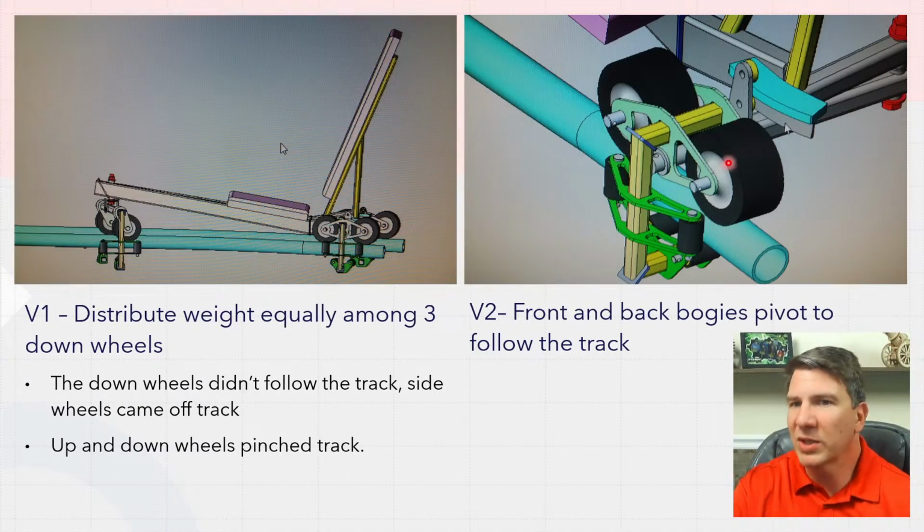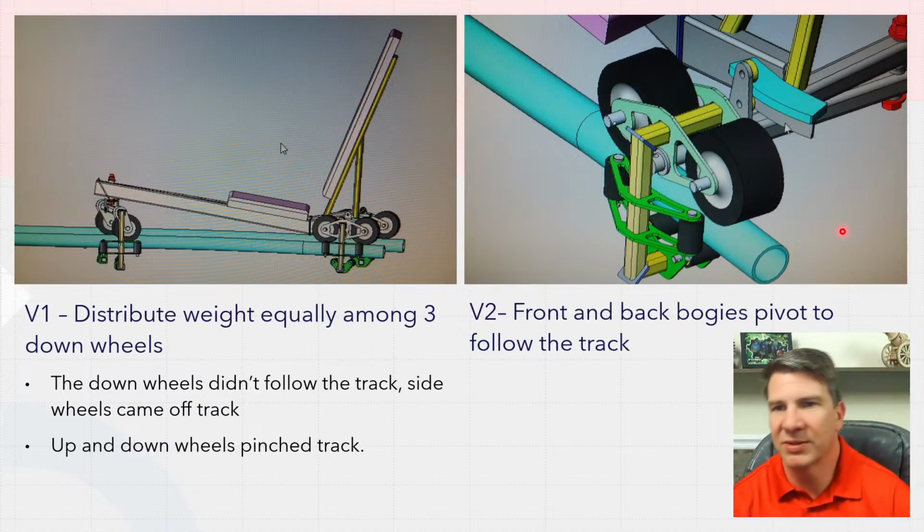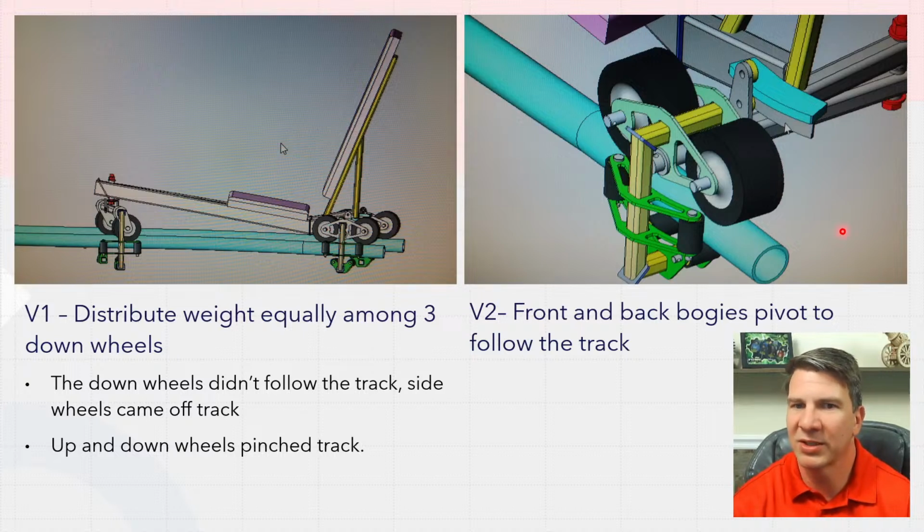All right, so moving on, you can see here, this is my rear axle. And the way I get the roll out of it, but still allow the yaw, yaw is turning, roll is the hammock thing, I've got a vertical pin here where the bogie, the lower one, can actually pivot. And I take out the reaction on that, the two yellow bearings there running against this blue crescent-shaped plate. That allows the back of it to take the hammock part out of it while still allowing it to turn.